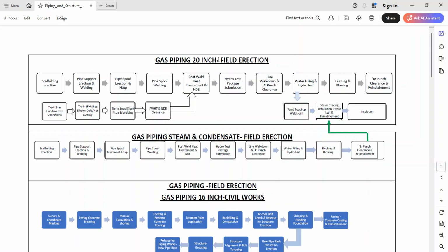Once the root welding is completed, there are different stages based on your thickness. You cannot fill the metal for a whole pipe at once, so you need to do it in stages. Everything will take some time. You need to discuss with your supervisors how much welding we can achieve per group, assuming two welders and two helpers. In piping we talk about inch dia. Inch dia is nothing but your pipe size or diameter. If it is a 12-inch pipe, we call it 12-inch dia.